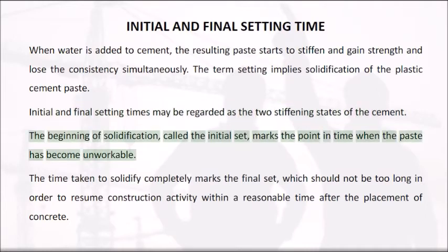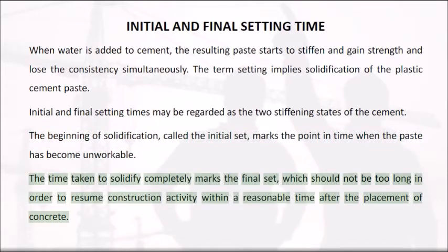The beginning of solidification, called the initial set, marks the point in time when the paste has become unworkable. The time taken to solidify completely marks the final set, which should not be too long, in order to resume construction activity within a reasonable time after the placement of concrete.